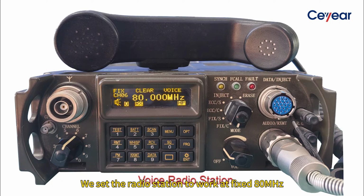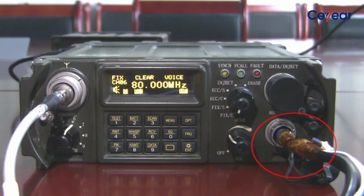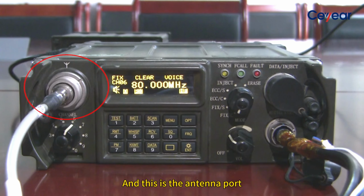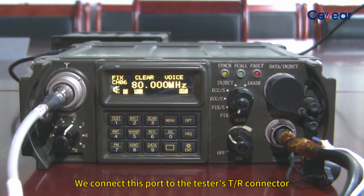We set the radio station to work at fixed 80 MHz. This is the audio port, including the voice input, output, and talk switch. This port will connect to the tester's audio in and out, and this is the internal port. We connect this port to the tester's TR connector.